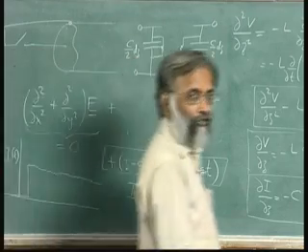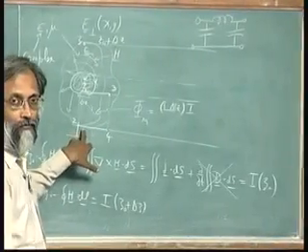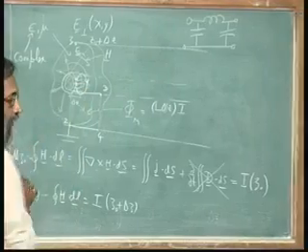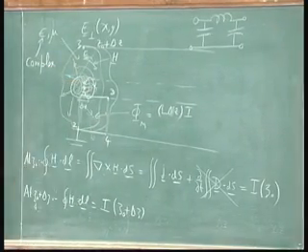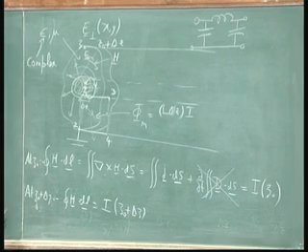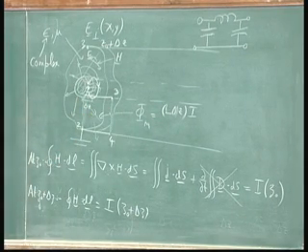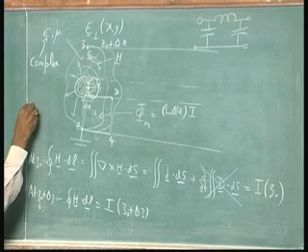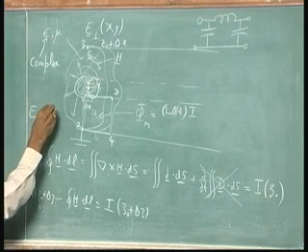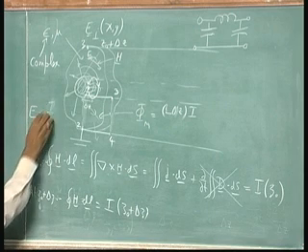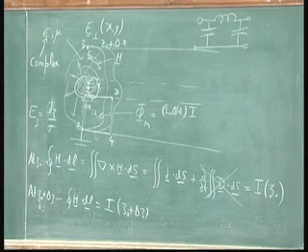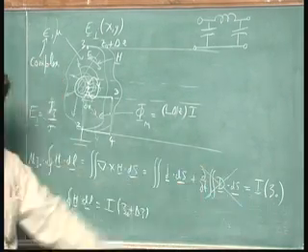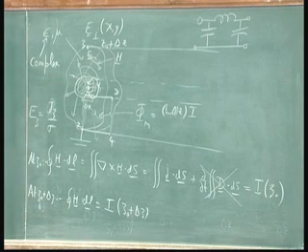The second kind of loss you have is in the wall itself, because you are having currents. These currents of course are travelling on the very edge of these wires because of skin effect, and as they flow you obviously have an electric field. You have an Ez which is equal to Jz divided by sigma, where Jz is equal to Iz divided by the volume over which the current is flowing.